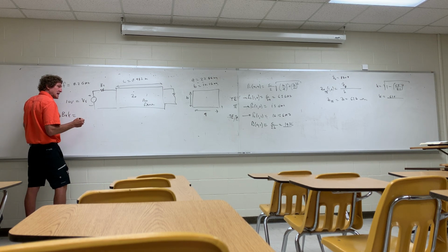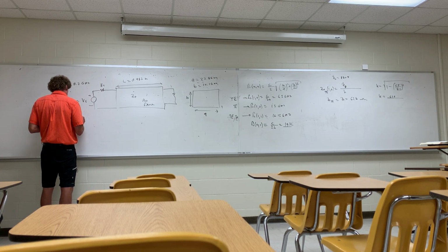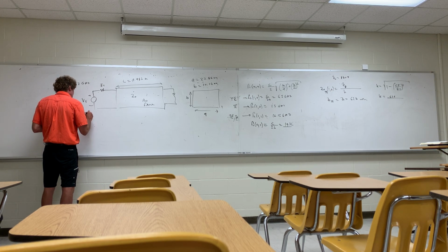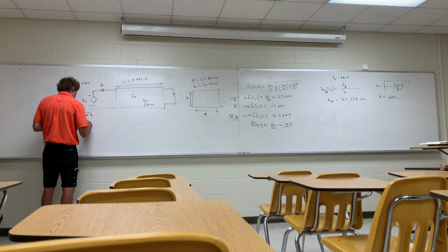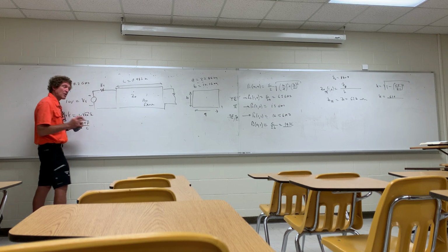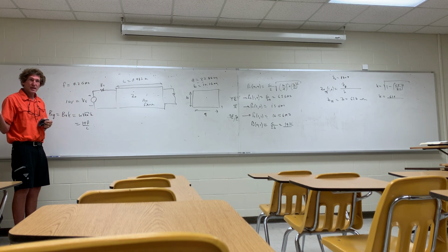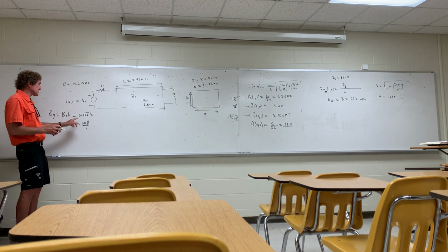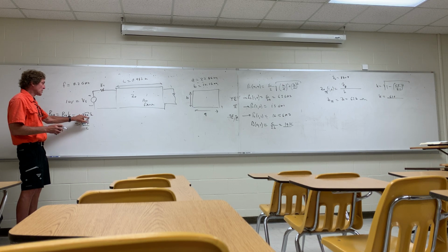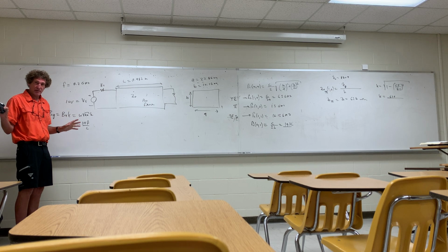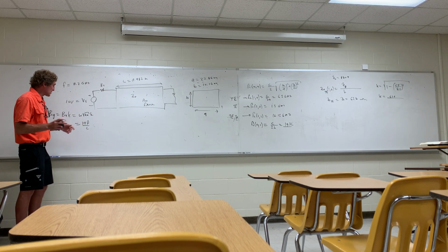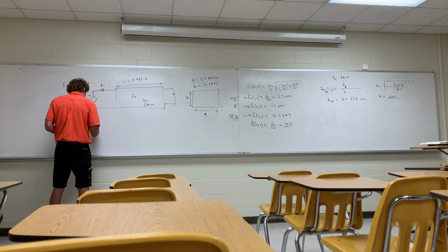So beta unguided is, well, it's really what? It's technically omega times square root of mu epsilon. Omega is 2 pi F, right? And square root of mu epsilon is 1 over C. Y'all follow me the way I'm doing this, class? I'm just showing you that omega square root of mu epsilon is beta for a lossless medium. It's the unguided beta. Now we have to multiply this by K.